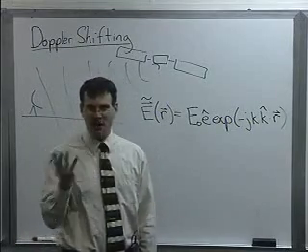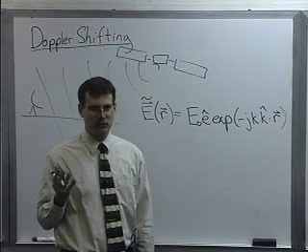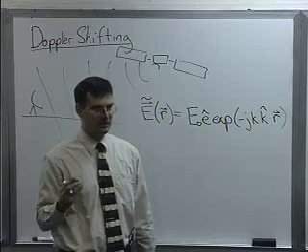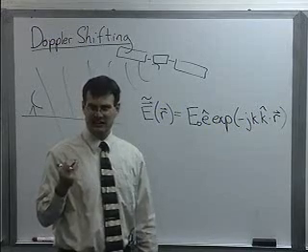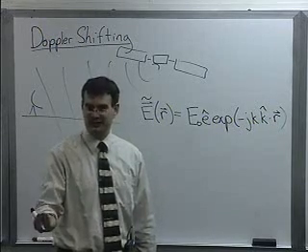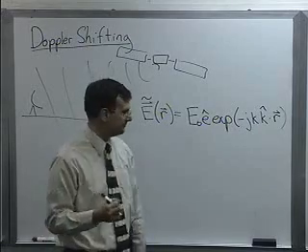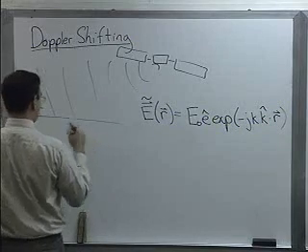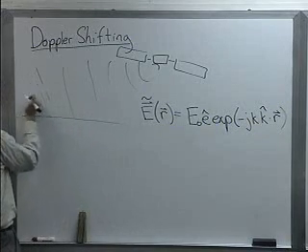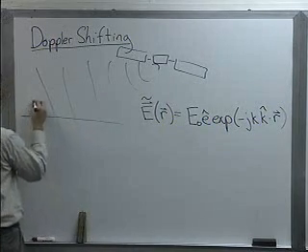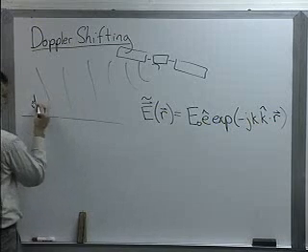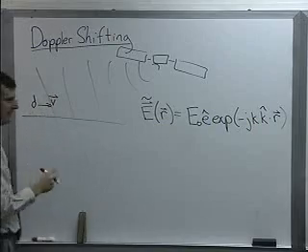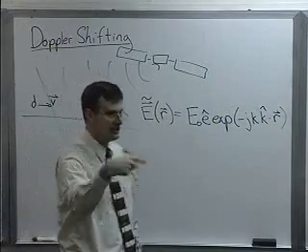However, COM people like to think of the channel in terms of time, because really the channel is like a black box to them. It's the temporal effects that it introduces on a time-varying signal that are what they really want to capture. And so in this case, let's say we have simple motion. Instead of a dish antenna, we've got some sort of handheld unit, say, and it's moving. It's got a velocity vector. It's a vector because it's got to have a speed in meters per second and a direction of travel.